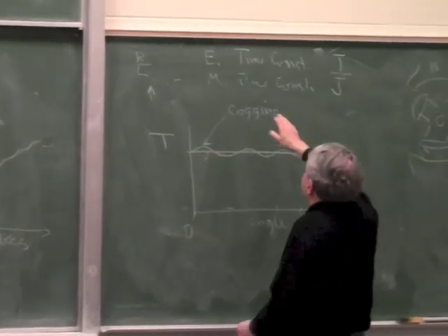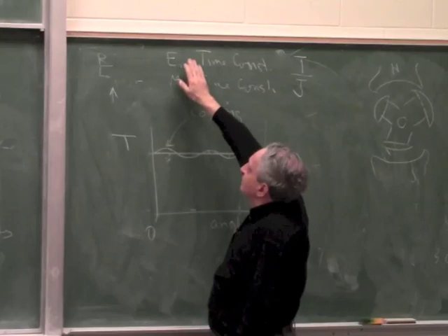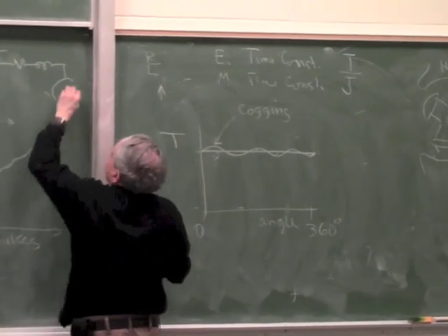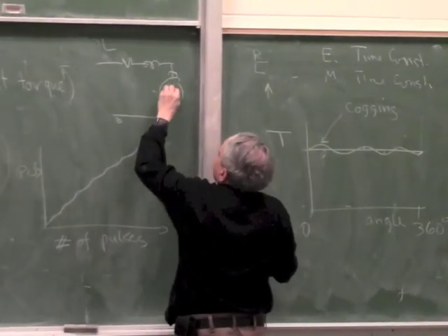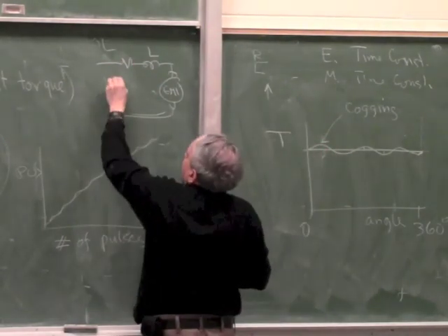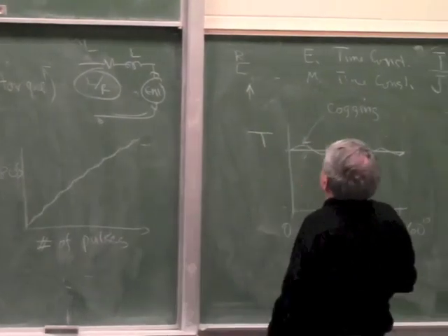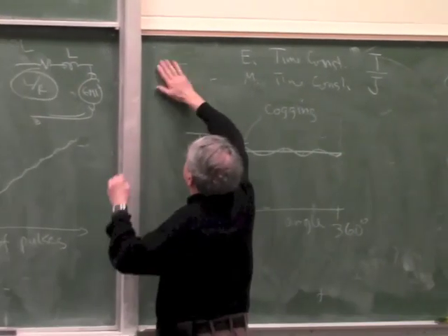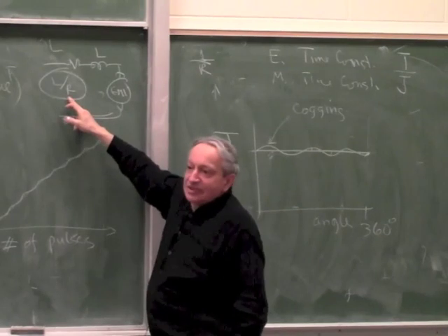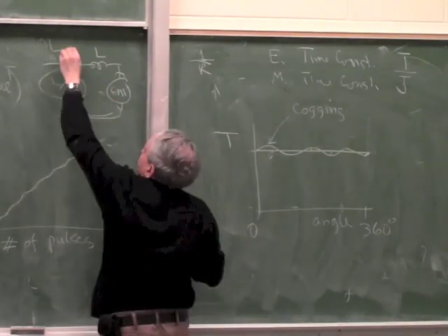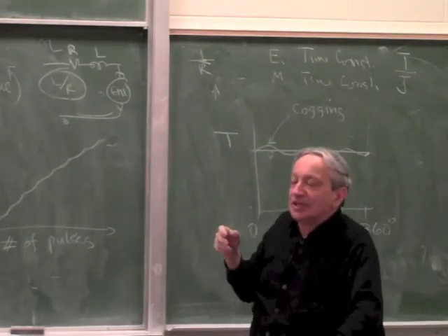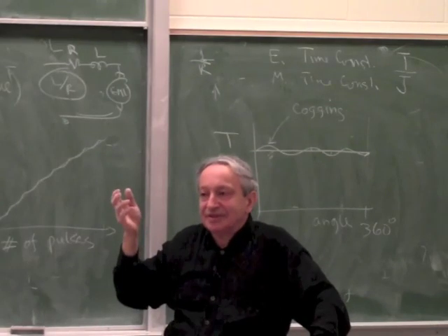So this is how fast it can accelerate, and this is how fast the current can go up, because the motor still has parasitic inductance, and this is the EMF. The parasitic inductance has a time constant, which is L over R, not R over L. So this L over R, which is the time constant of an inductor, this is R, this is L, determines how fast the current can come up, because the torque cannot develop until the current came up. Is that clear to everybody?